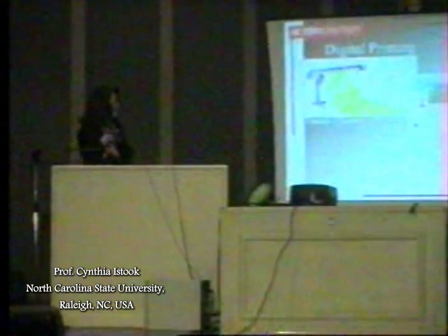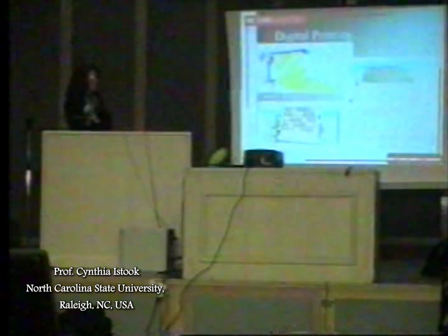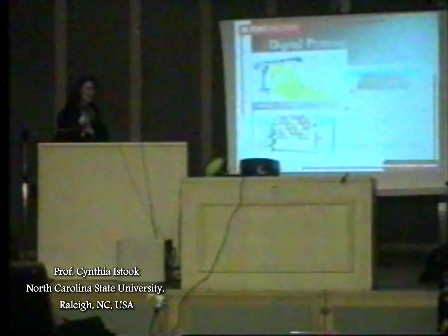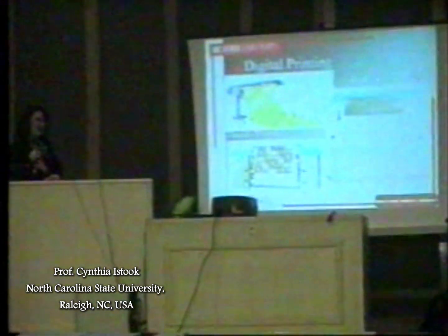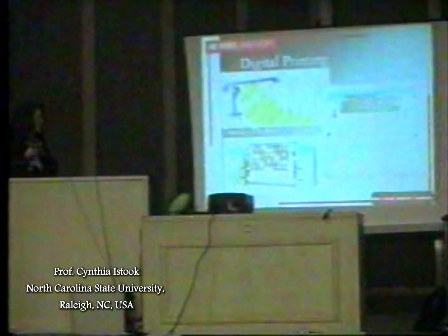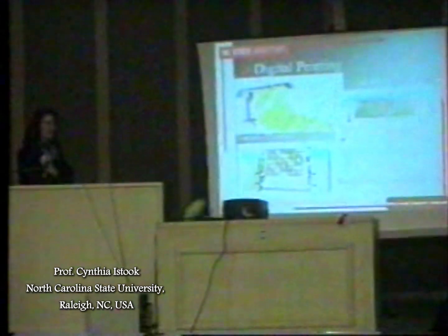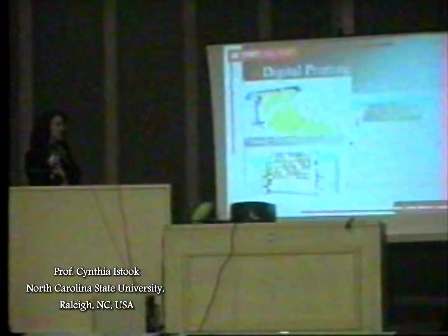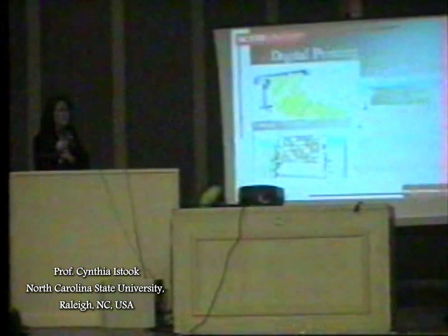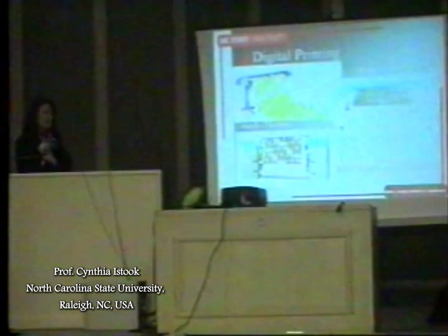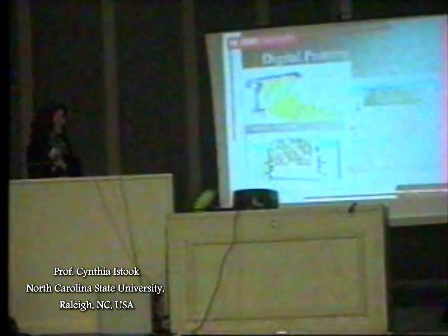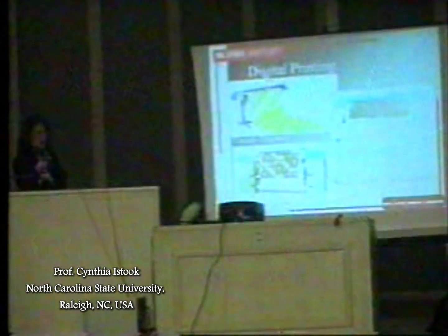And then we have the Stork Amber, which is a piezoelectric printer, which uses electrical charges to force a drop of ink out. And the third major technology is continuous inkjet printing. It's a little bit like a water hose that sprays the ink continuously and deflects a few drops towards the substrate as you need them. And the problem with this technology is that it requires continuously reusing the ink that's not being applied to the substrate, which means that ink has to be very refined. And it's an expensive technology, but very fast. So we could create hundreds of yards a minute rather than a yard and a half an hour.